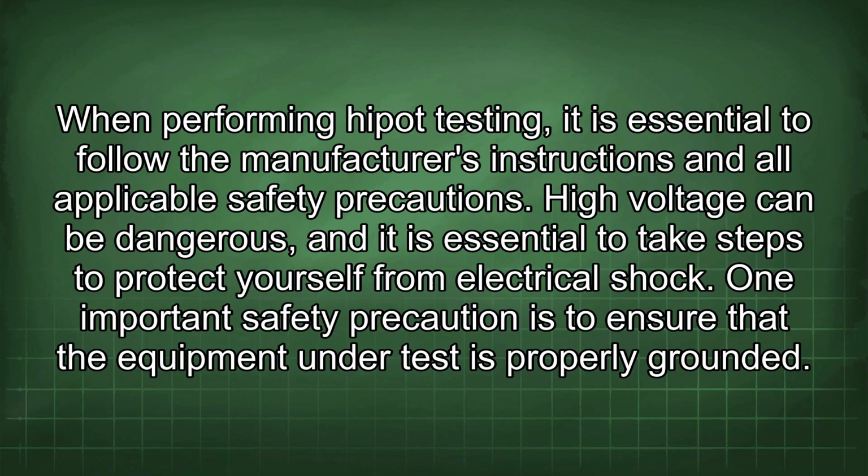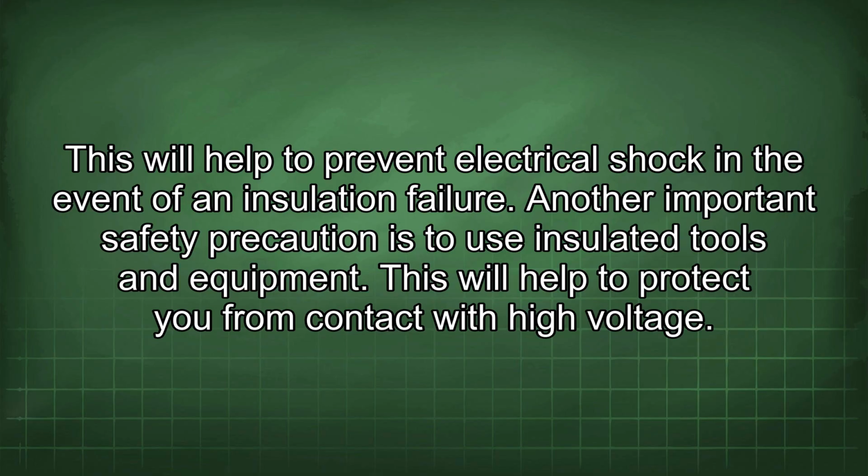When performing Hipot testing, it is essential to follow the manufacturer's instructions and all applicable safety precautions. High voltage can be dangerous, and it is essential to take steps to protect yourself from electrical shock. One important safety precaution is to ensure that the equipment under test is properly grounded. This will help to prevent electrical shock in the event of an insulation failure. Another important safety precaution is to use insulated tools and equipment. This will help to protect you from contact with high voltage.